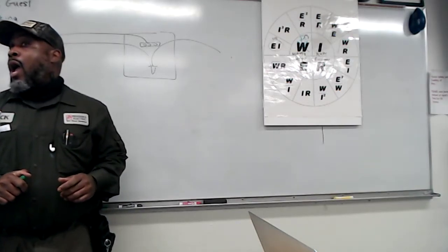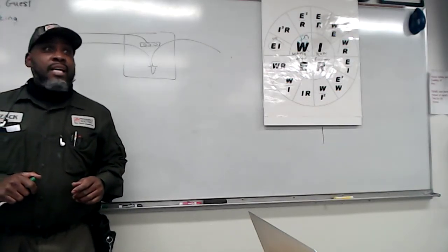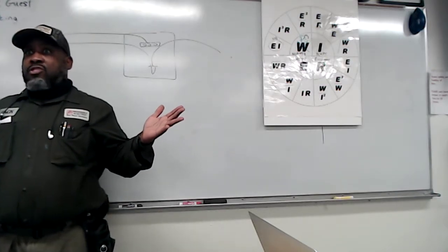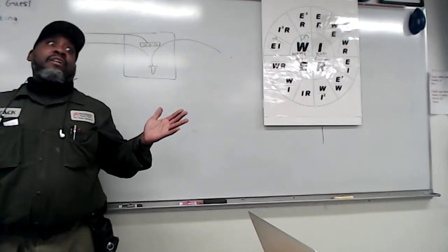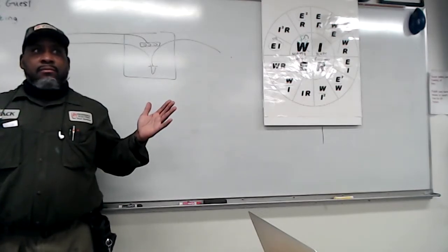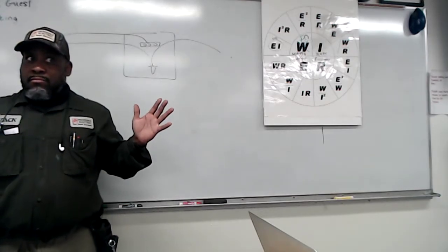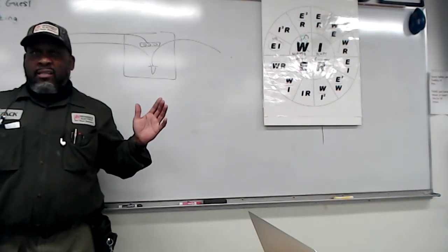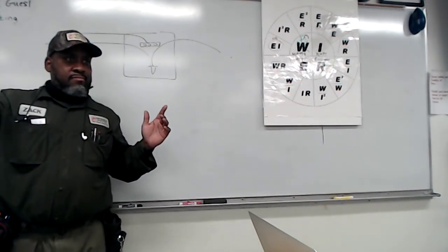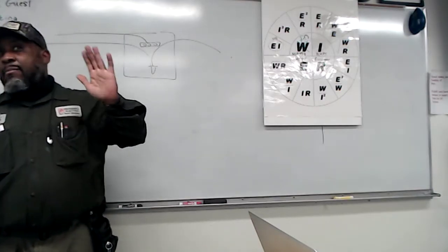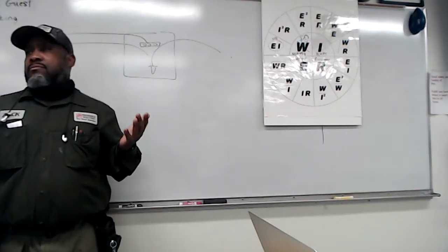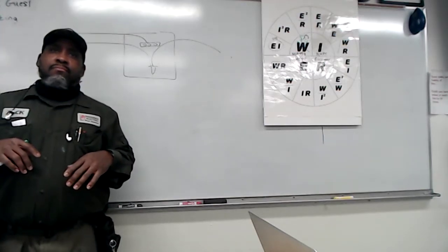So you get crimps and things pushed in the box. If it gets jammed in, what is going to happen? It's just going to ground the box better, not a current carrying conductor. So what happens with a current carrying conductor then? You can arc it over. It's going to short out. If I jam in a neutral, it could short out. Does that make sense?